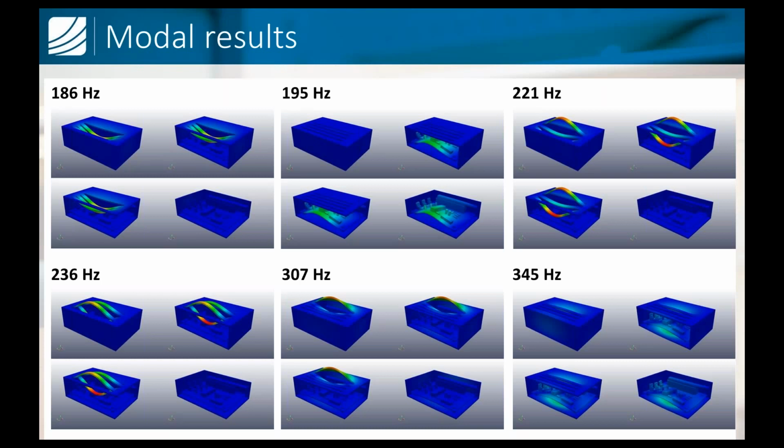In this case, we can gain credibility with our customer or business partner and say, look, if you put your PCB board in this configuration in your machine, it may start bending. It might break. So we propose either to add additional mounting, if he agrees, or he should change the design. At the same time, we still observe that up to 270 or 300 Hertz, there's quite a lot happening with our separators. A simple, fast analysis gave us the understanding that we need to do something with the connectors.